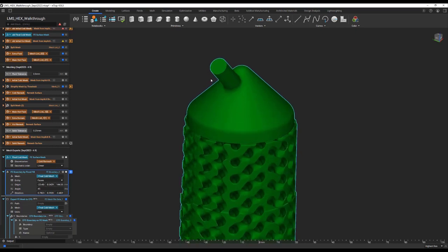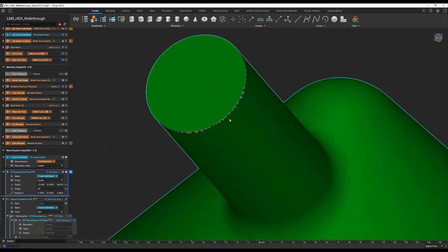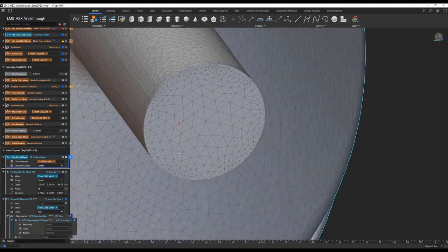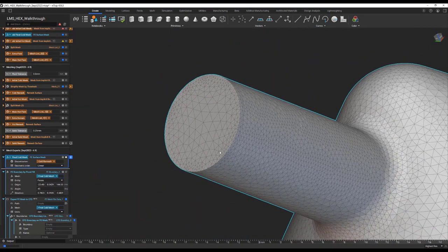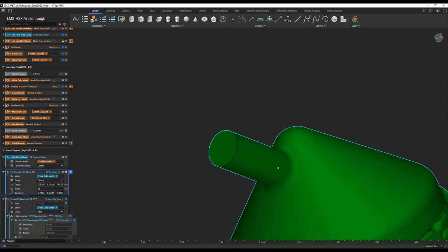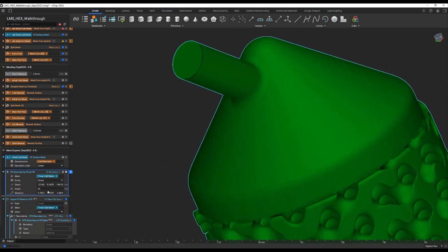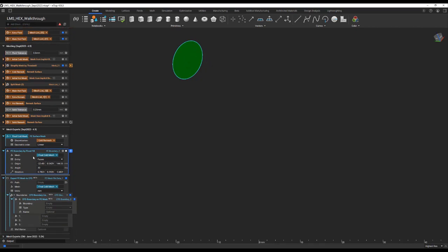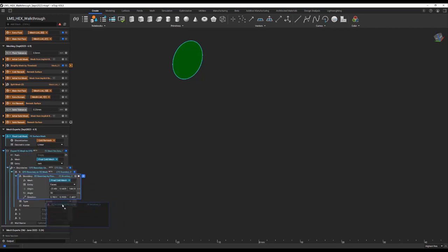And depending on how well this edge is captured, if there are small deviations in elements, especially the angle, like you saw, you might capture more of the geometry than you want. So generally, I'll come back to this angle value and drop it down to about 30, and that just forces that block to only capture these elements. We'll drag the FE boundary into this block.